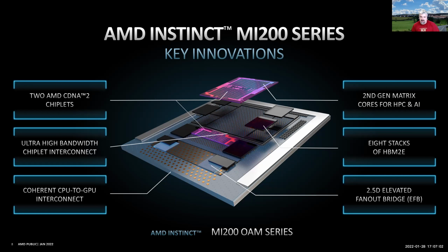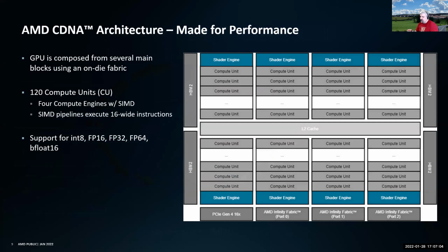And the compute dies themselves roughly look like this. So consider this a floor plan. It's actually MI100, but the MI200 design is very similar to that. So basically, you can see the attached HBM modules, the memory controllers, and even though I said this is no longer a GPU in the traditional sense for graphics, there are still some concepts showing up, like the main control unit is still called the shader engine, even though there are no longer shader units in the whole design.